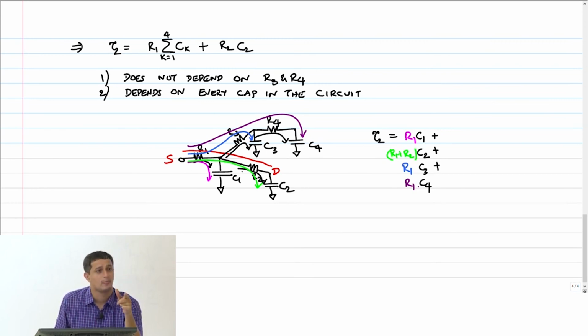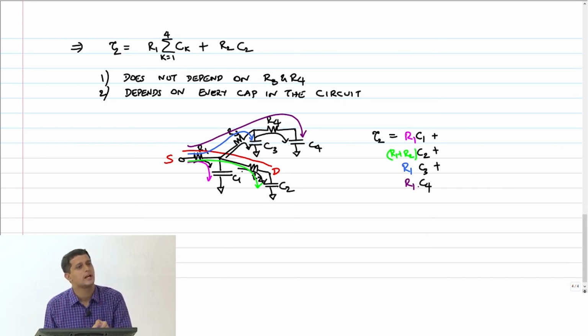What you should check is maybe this first order approximation doesn't work at some very high limits. That you should check through simulation, and that may break. From the first order approximation we are getting this. That is for maybe there is a reasonable range of resistors and capacitors where this works. That you have to go and double check in simulation where it fails.